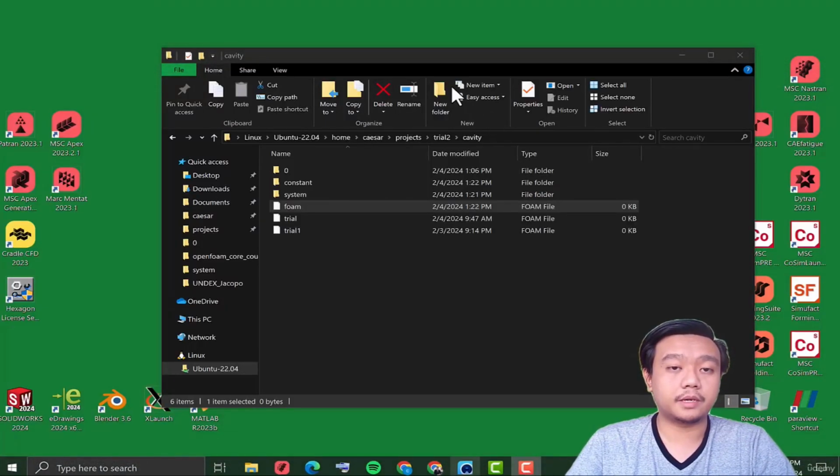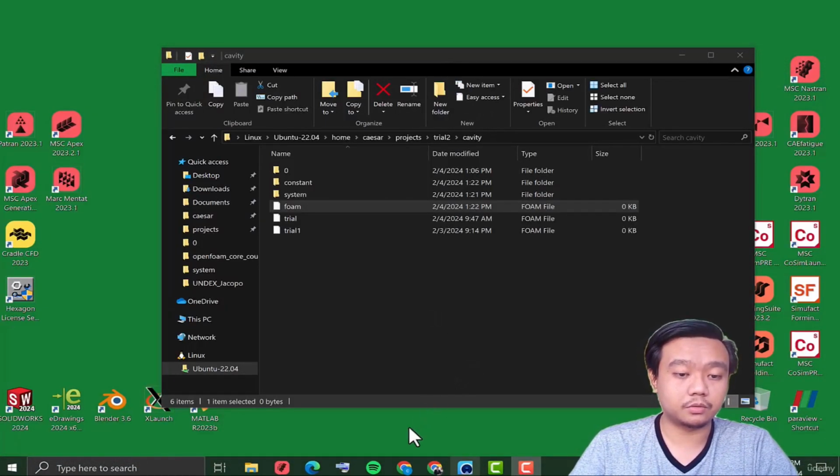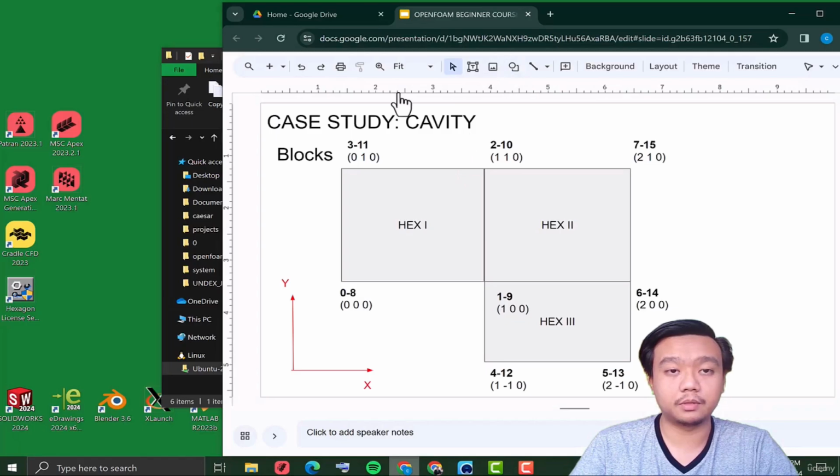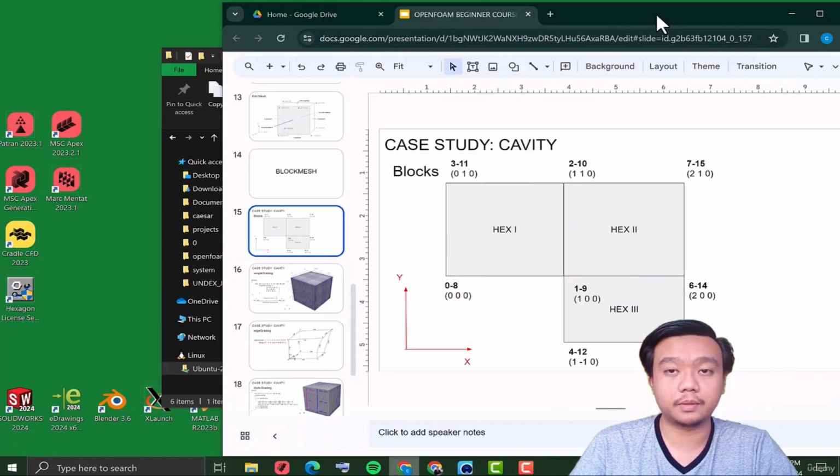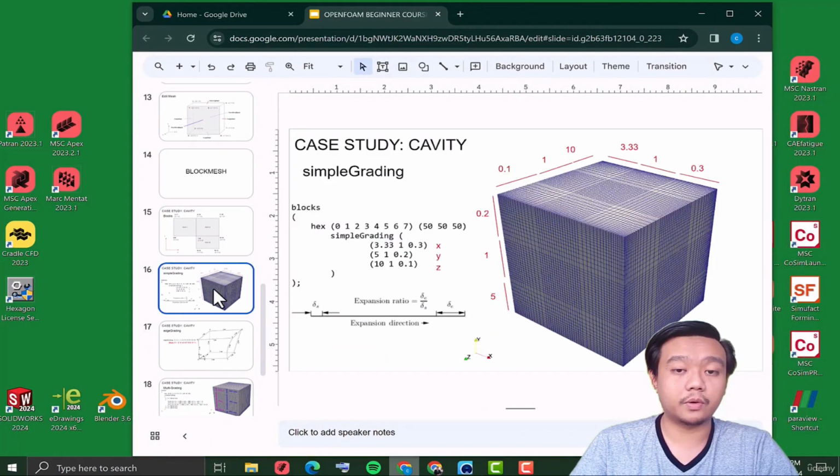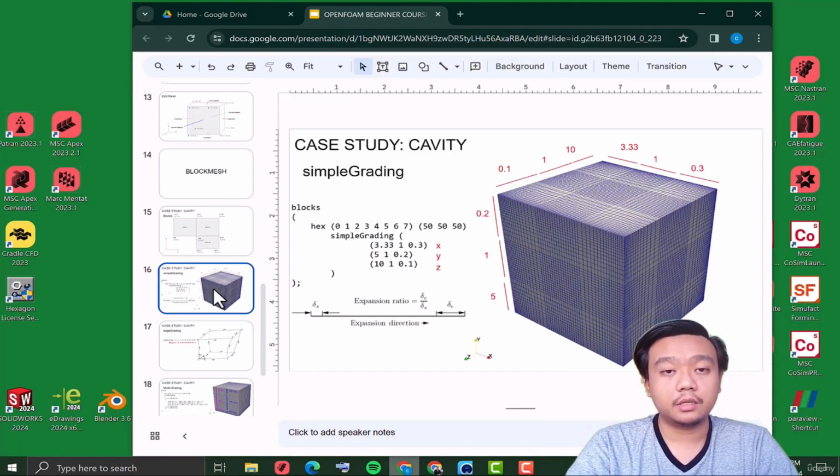Okay, in this part of this video, I would like to discuss more detail about the block mesh, specifically about the use of grading. The grading is very useful if you want to make an efficient mesh. Let's say you want to focus only on the near wall boundary layer.